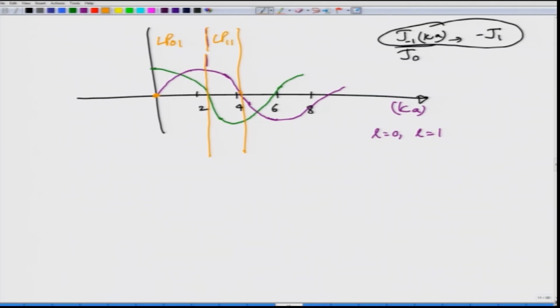But from our previous discussion, you also know that in this range you actually have the true solutions, which are TE01, TM01 and HE21 as well. So, what you can actually see is that LP11 is a linear combination of 3 modes, TE01, TM01 and HE21. Okay. So, by combining appropriately these 3 modes, you can obtain different LP modes.